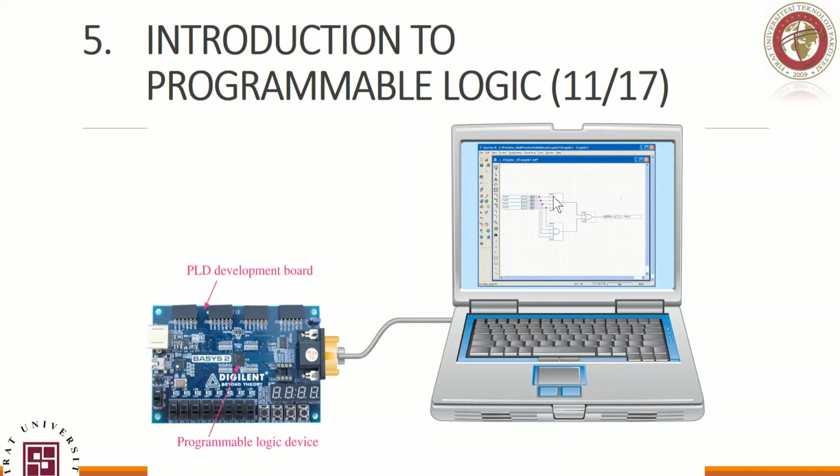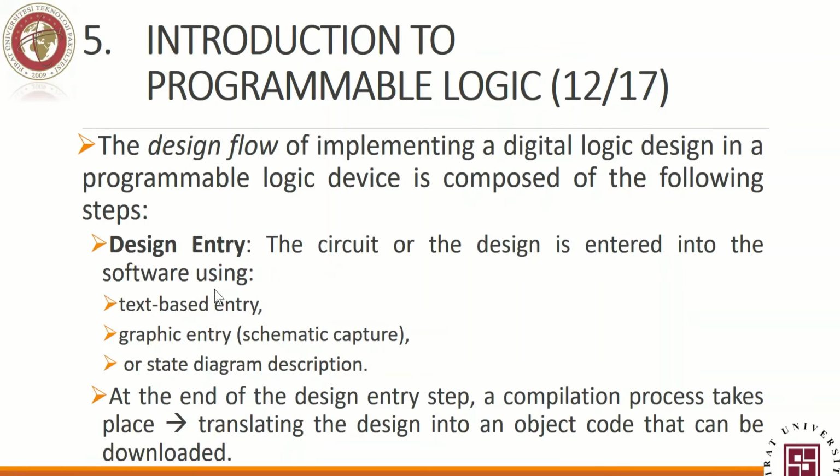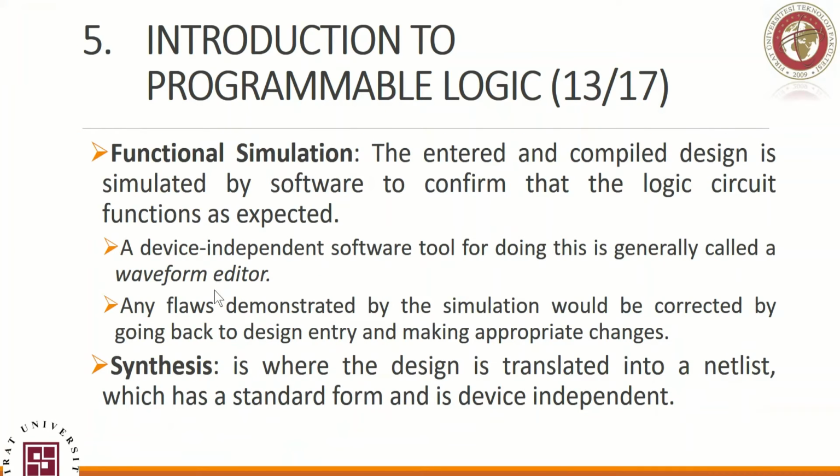Is that practical? No. In that case, you need to attach a ROM to it. ROM, read-only memory, a memory that holds this design and keeps it. When the electricity kicks in, it loads the program back again to the PLD. It's very similar to the BIOS of our system.